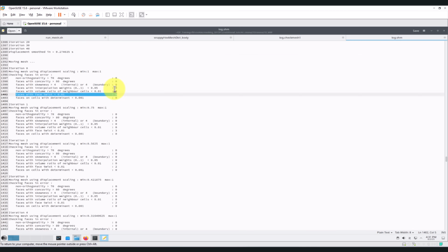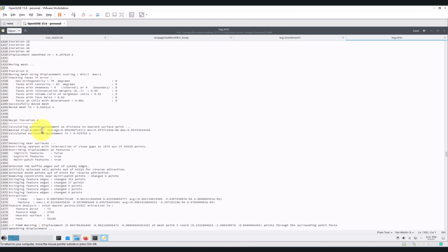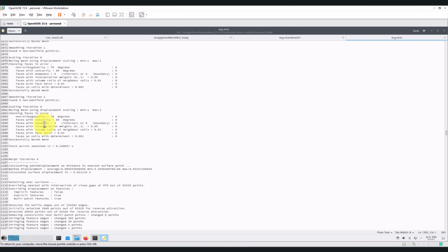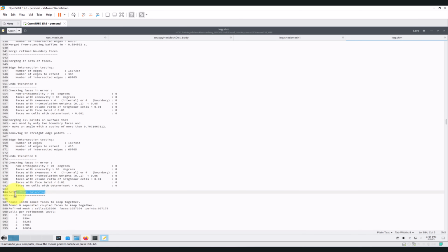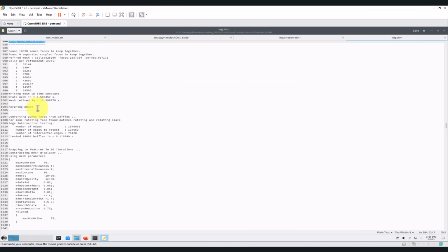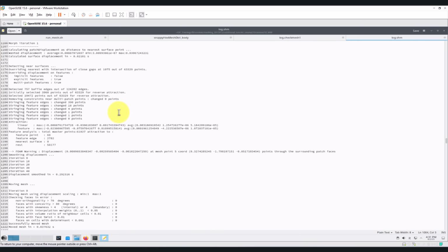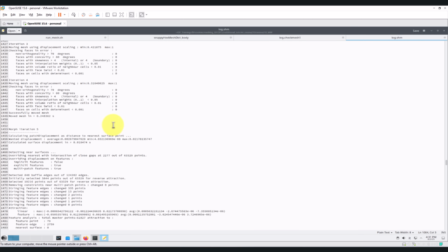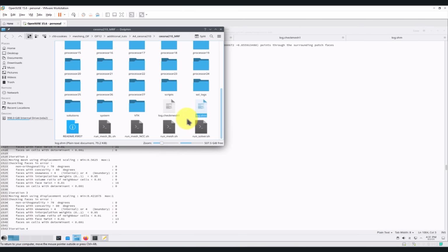Actually, you have that, and I think I already was in the, okay, yeah, we were already here in the morphing stage. Now we were doing the snapping. So let me go here. Okay, so final balancing. This is for the previous step, and now I start to do the snapping, and here's where you start to see that bad quality. That is not that bad. And what it's doing now, every single iteration that you see here, is just trying to enforce the mesh quality criteria that you are defining in the mesh quality dictionary.